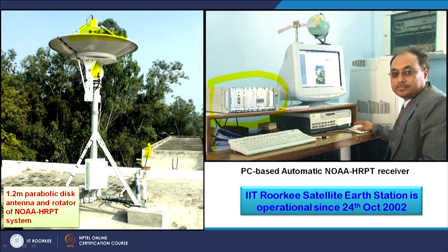Because as you know, these computers have a backup battery that may deteriorate with time, and the system clock may be delayed by a few seconds or a minute. Whereas for data acquisition from a satellite, the system clock has to be very accurate, like atomic clocks, which is only possible if we get the data from GNSS satellites or a GNSS receiver.